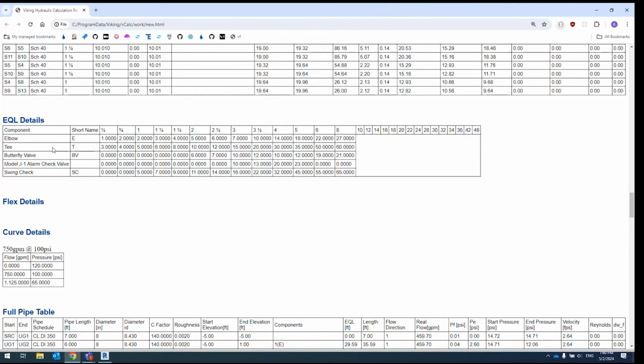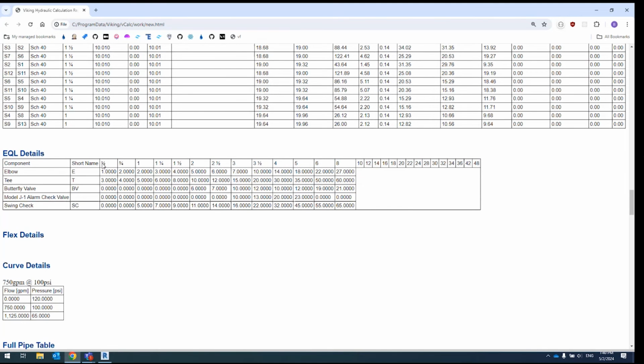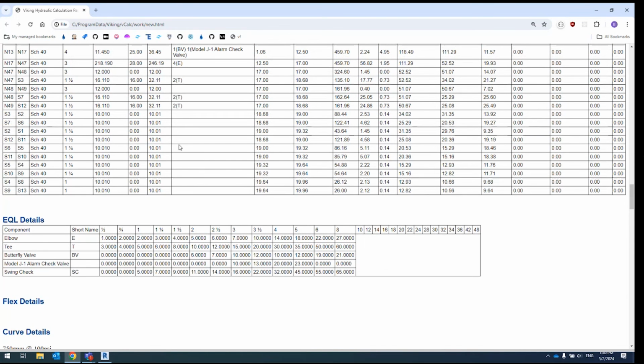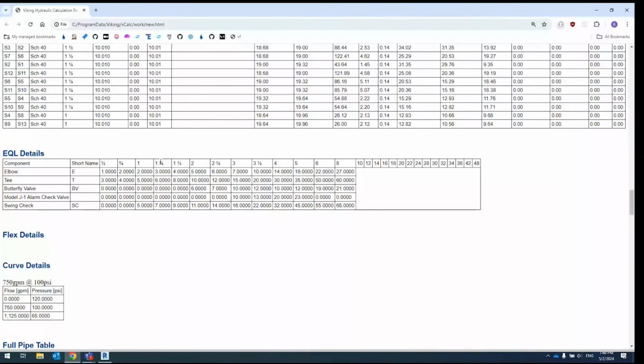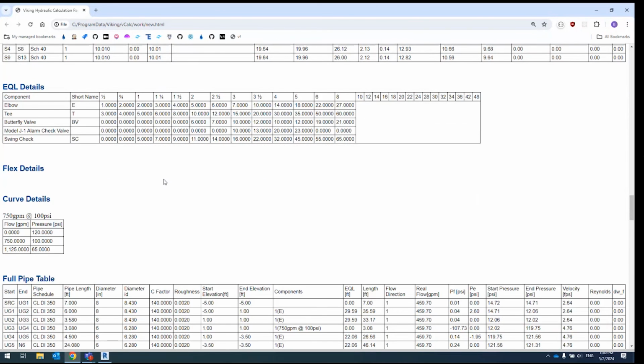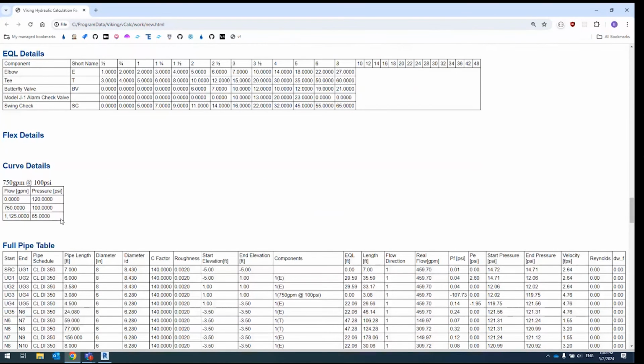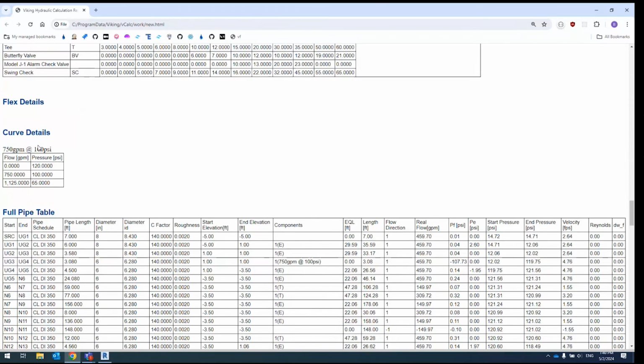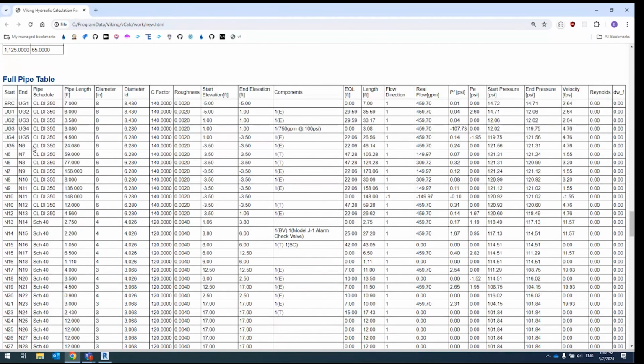So you can see in this table here, the equivalent length for each nominal diameter for a T, for an elbow. And this will let you cross-reference with the tables above, just to figure out what we utilized for the basis there if it wasn't clear. And it's a similar idea with the pumps or anything that's curve-based, like a backflow preventer. We'll include all the X and Y coordinates that built out that curve. So, full transparency on the data input there.